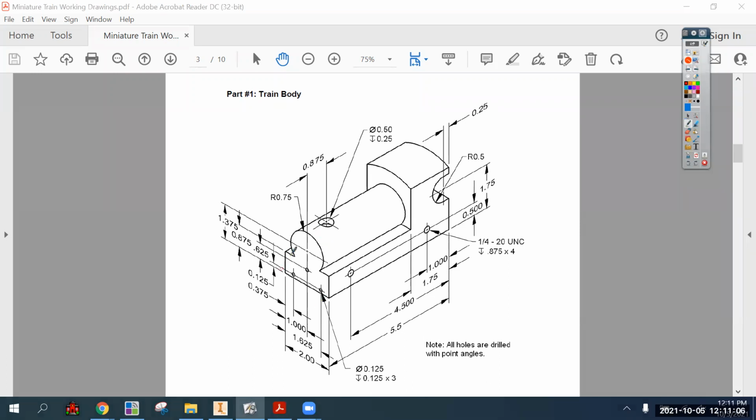The path for this, I would say, is make this shape right here, which is a rectangle and a circle, even though this arc right here is dimensioned by its radius, because when it's done, it is an arc. We are going to use the full circle tool with a diameter that's twice that. We try to lean towards rectangle and circle rather than lines and arcs, because they'll always be closed loops and easy to extrude.